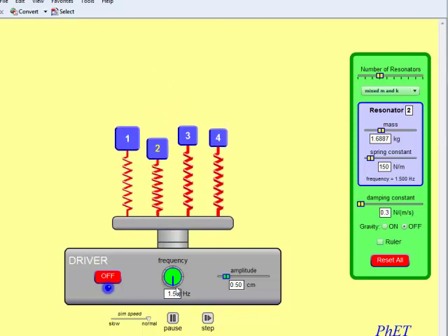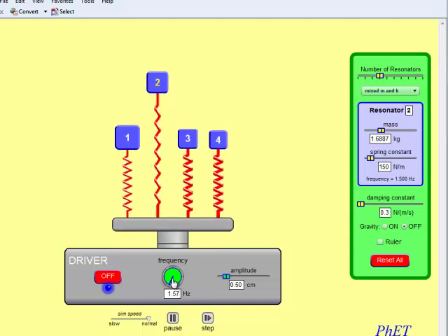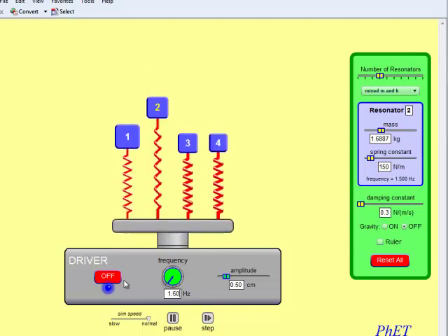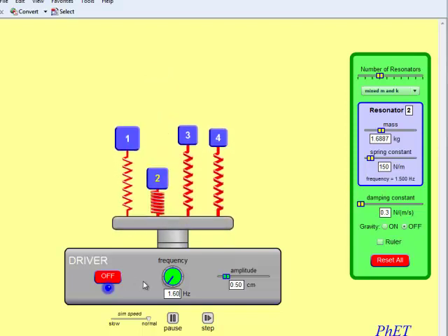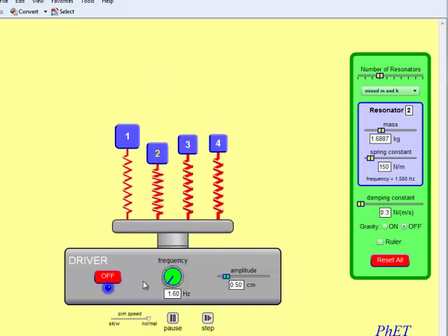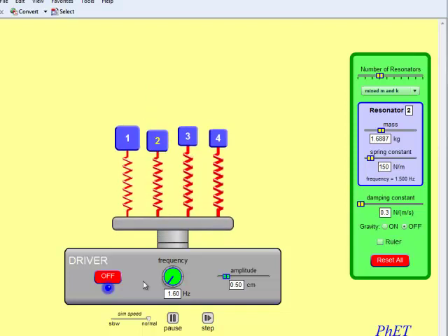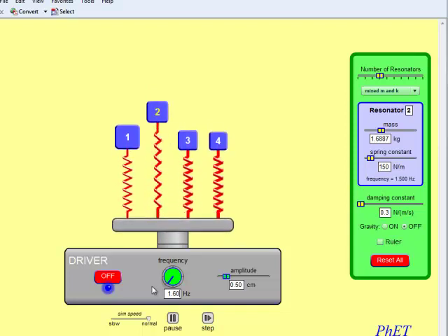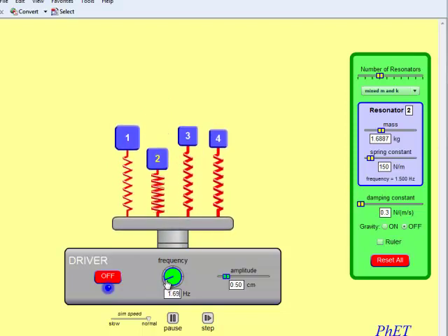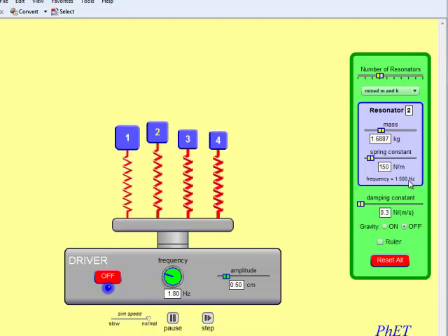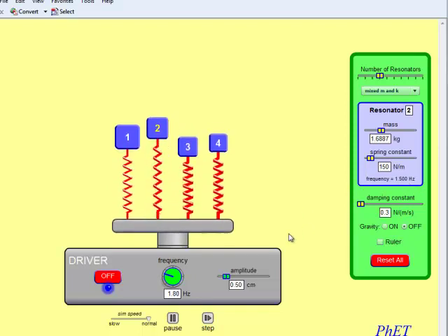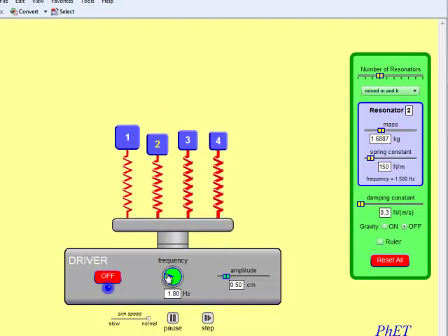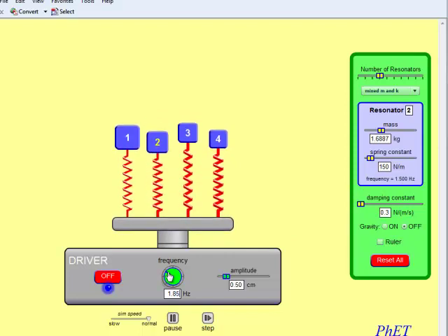So there we go. And if I move it a little bit away from it to like 1.6, even though the damping is small, it actually calms down. It's going to do it again where we'll see this beat that we saw in an earlier recording. By the way, I do realize that I have given away here already the natural frequency of it, but I wanted to show how it can be calculated to see what would lead to that catastrophe.